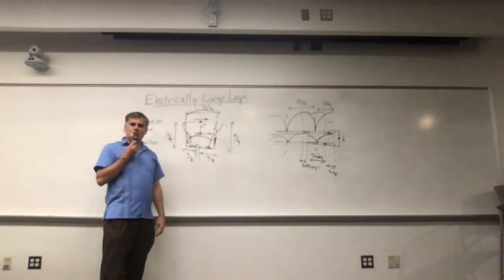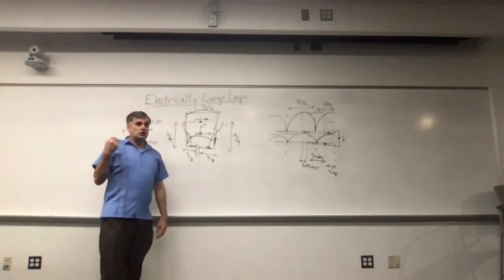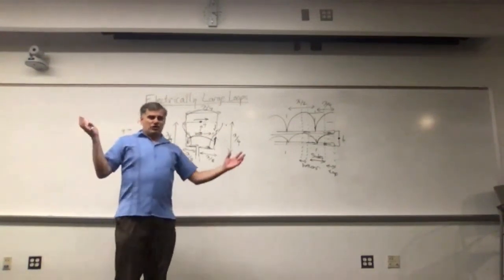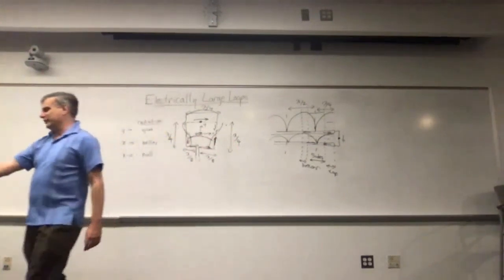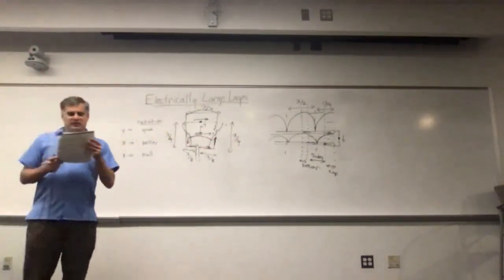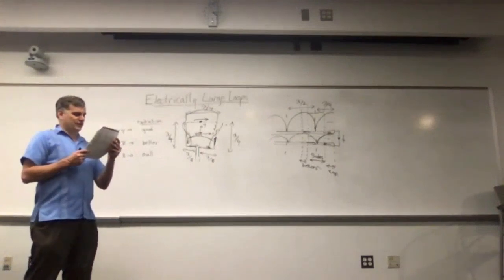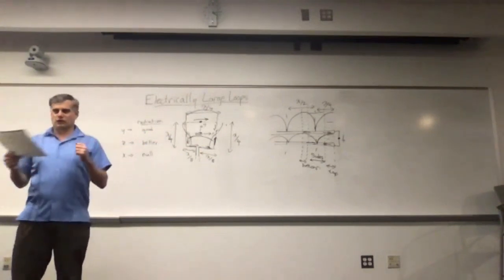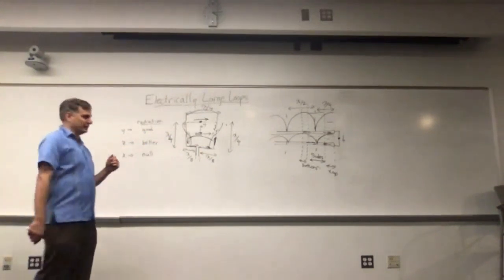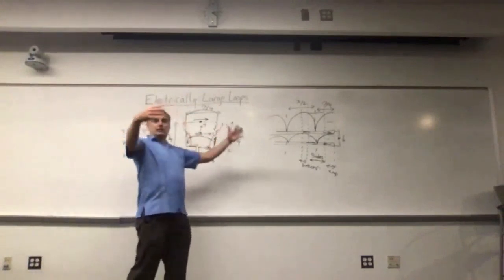Might even have you do a homework problem. But that also resonates again. The reactive component collapses. You get a large real value. And according to Stutzman, that real value is closer to 200 ohms or higher, over twice what the 1 wavelength loop is. And you can keep on enlarging it.